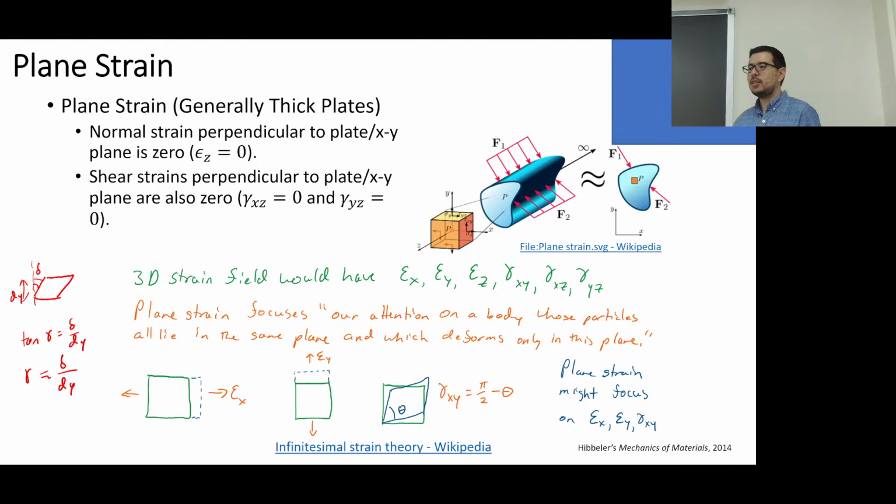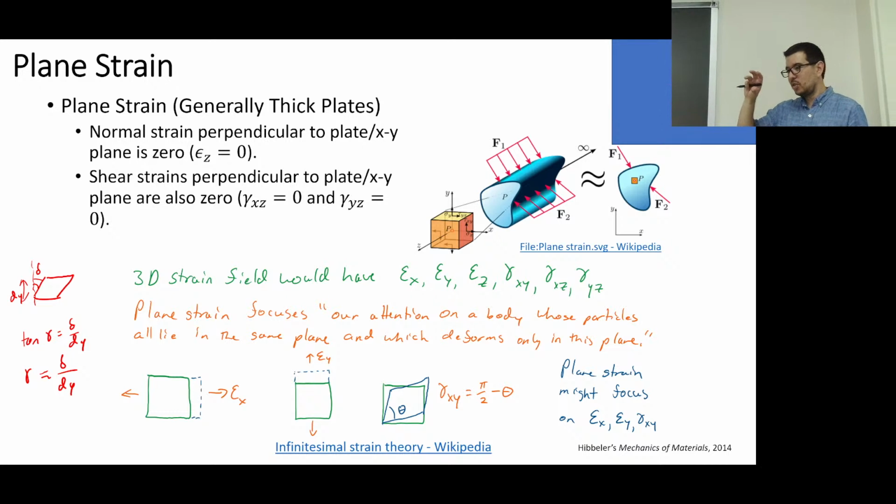We were just talking about how we know that sigma 3 is equal to sigma z is equal to 0. Andrew, you were just asking that question. It is because the other slots in that tensor are equal to 0: the tau xy, the tau xz, the tau yz, the sigma z.